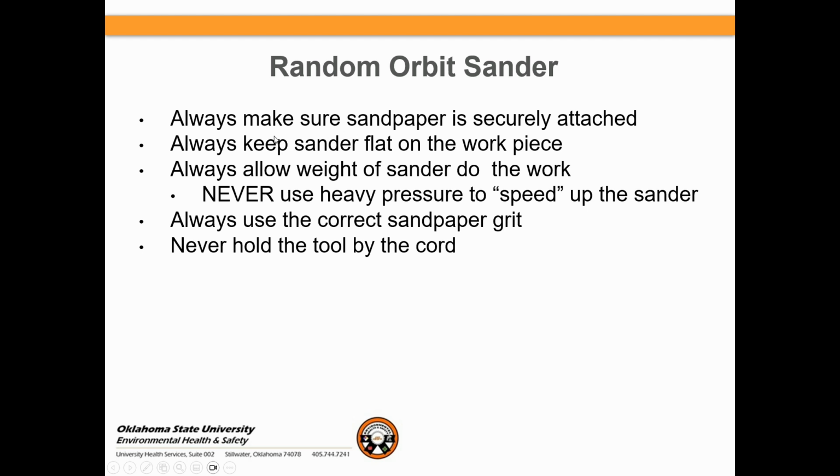The random orbital sander, once again: always make sure your sandpaper is securely attached. Always keep the sander flat on the workpiece. Always allow the weight of the sander to do the work, and never put any heavy pressure on it to speed up the sander. The other thing too is always use the correct sandpaper grit. And the other most important thing is never hold the tool by the cord.